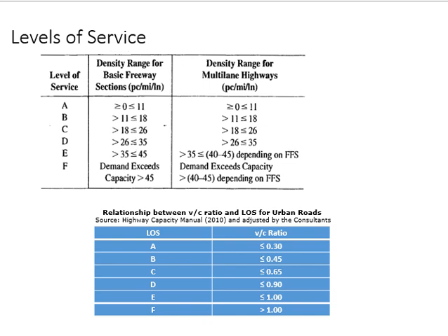Now this is something different. It is taken from the old manual. I haven't found it in the new manual. I did not even find it in the old manual. They are using it in the market, in consultancy, somehow. But here instead of density, they are saying level of service is according to V by C ratio. V means flow rate, C means capacity.